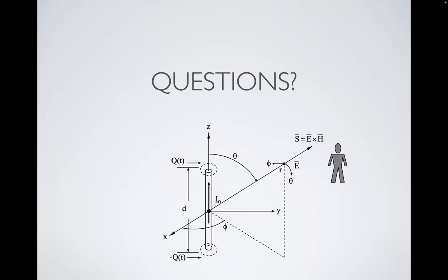A minimum of a quarter wavelength, I would say; somewhere between a quarter and a half is adequate. Yeah, all the same length, unless you want the pattern to go one way or the other. That's another thing. But if you want an omnidirectional pattern, you want them all the same length. And a minimum of 16 on 40 meters. Yeah, it's a minimum of 16. And then when you get to above 30, it starts to diminish, but not before.